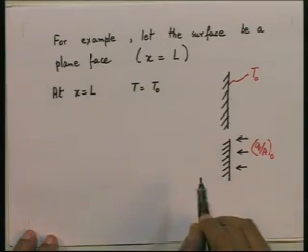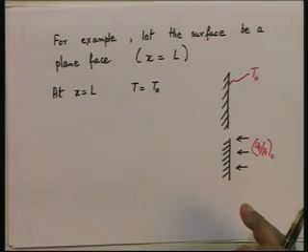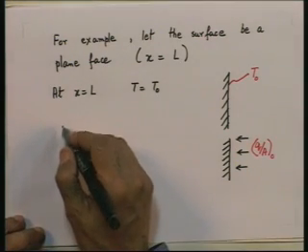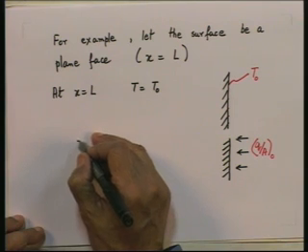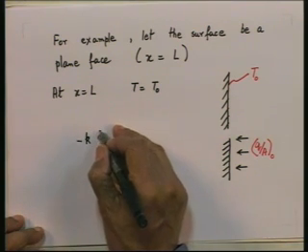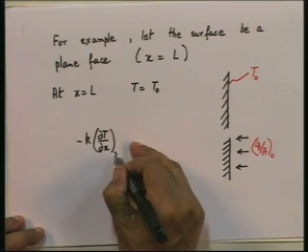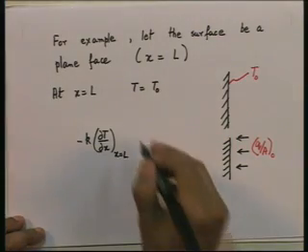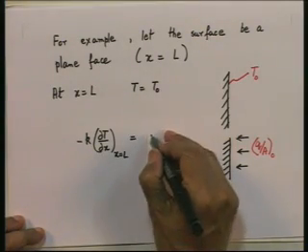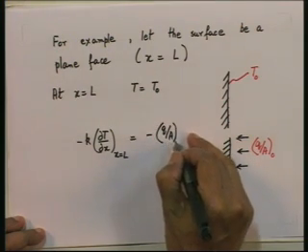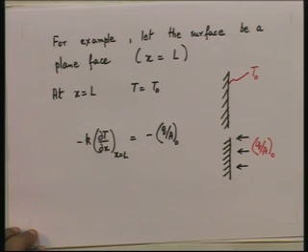So, we equate this flux to the heat flux we will get from Fourier's law of heat conduction at x equal to L. The prescribed heat flux can be stated as minus k dT/dx at x equal to L is equal to minus q by A naught. This is how the second type of condition would be specified.